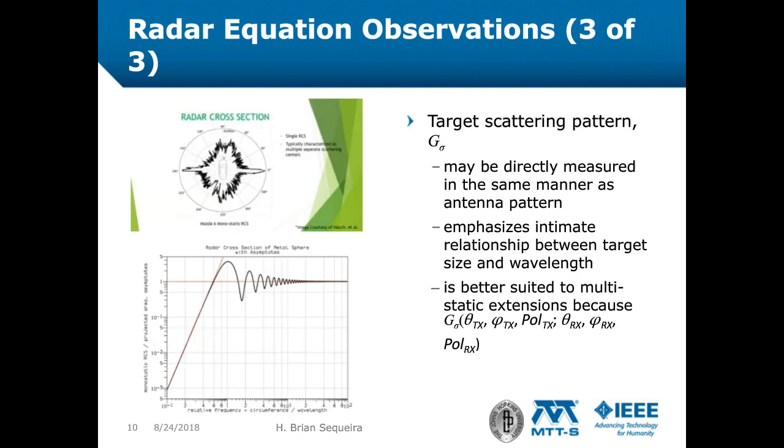An antenna of a specified shape has a pattern associated with its size and shape, and that pattern varies with viewing aspect to the antenna. Like an antenna, any other object has associated with its shape a scattering pattern and a "gain" that is denoted by G sub sigma, which is directly accessible to measurement as is with an antenna. So we use G sub sigma to unify the concepts of scattering to antenna and target alike.